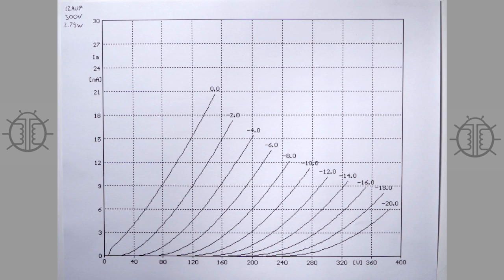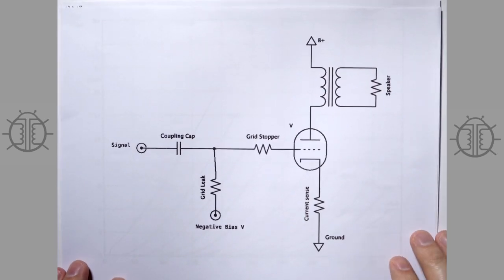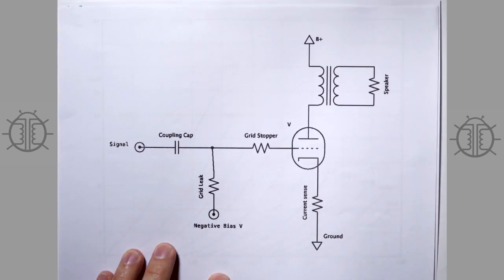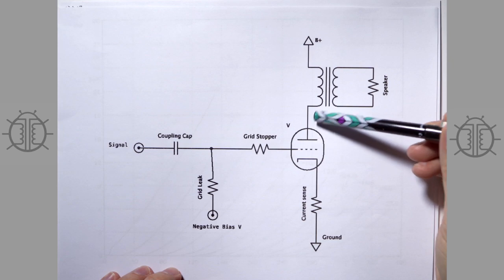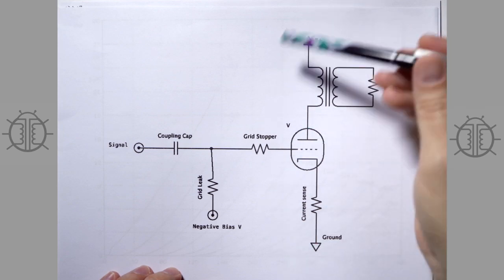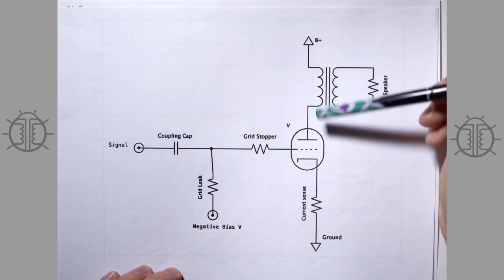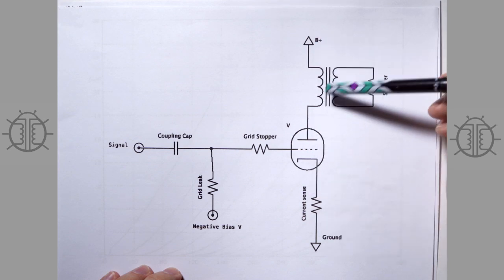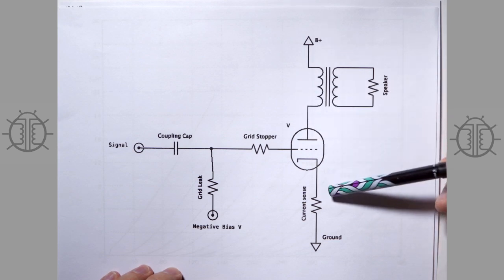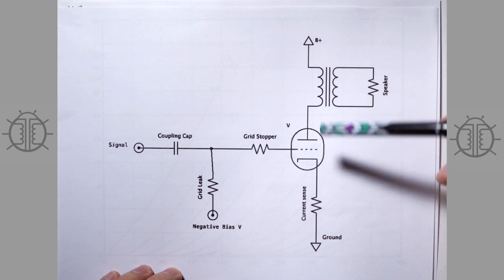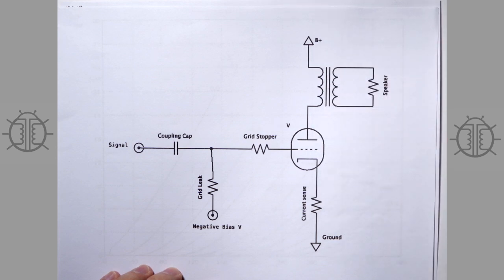First of all, let's remember what an amplifier looks like, so we know what the context is here. You can see that this is like an output stage, and the voltages and currents we're going to be talking about are happening at this point. It's part of a greater system. It's half of a voltage and current divider. So when we see, for instance, voltage on the plate swing up but the current swing down, just remember that the reason it's doing that is because it's part of a divider.